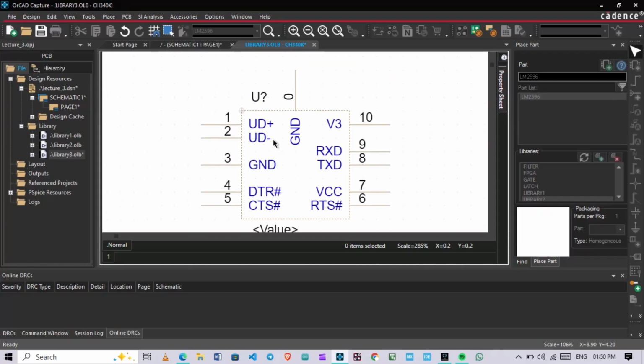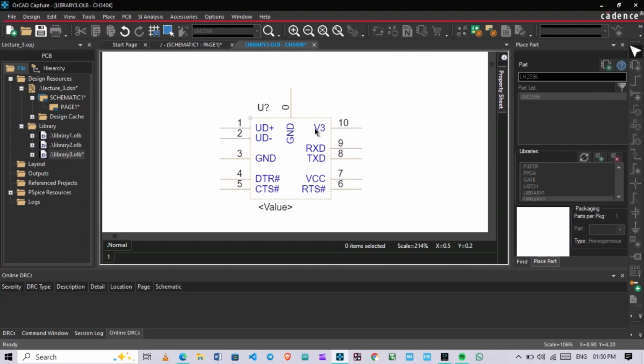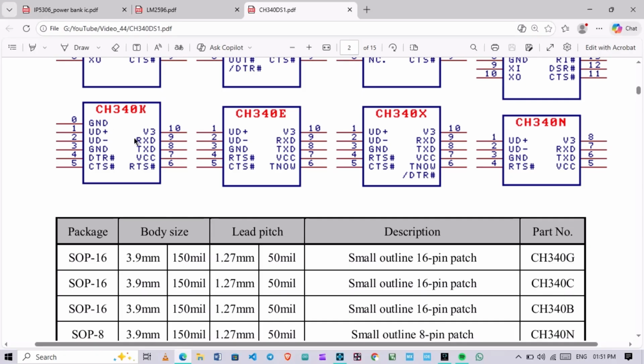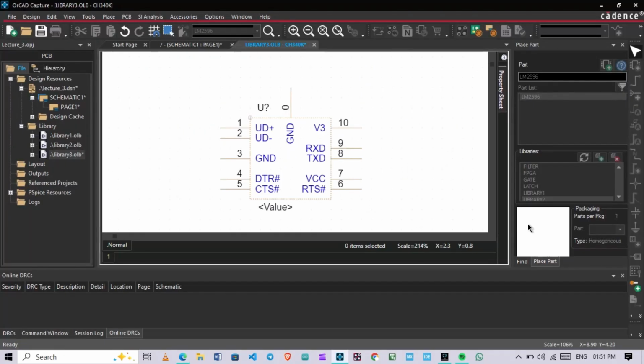Also you have to use it like that whenever a larger number of pins are there on the schematic symbol, sorry, in the library creation, the component library. You have to create it like that, so it will look clear and more professional also. So this is the ground 0 pin, you can consider it a common center pin. This is a common ground pad for dissipating the heat only. Now I have created all the pins using these pin names. So now finally we have to provide the outline.